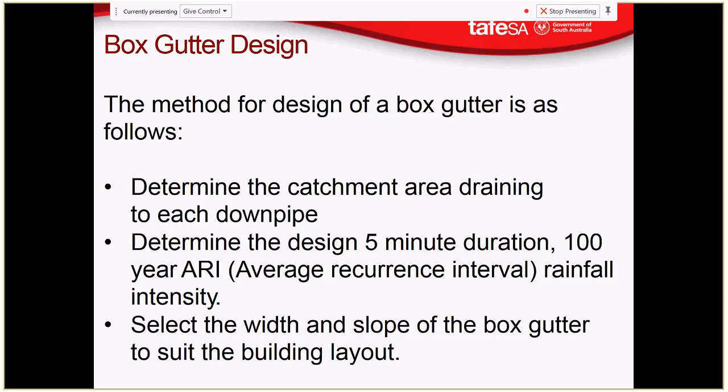Yeah, but in this scenario, how would you be pumping the water up the hill of the land or something? Yeah, with a little submersible pump. So it's a pump that has a float on it. It's a pump that can sit underwater, and when the water rises, the float arm lifts up like this, and it turns it on, and it pumps the water out. And when it's pumped the water out, the float goes down, and the pump turns off again. Just like the water system in the toilets. Yeah, like that in reverse. Exactly. And those pumps are really cheap. They're quite cheap to buy. But they fail at some point in time, and I've seen a few failures.